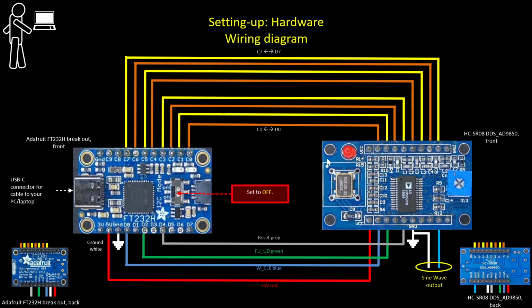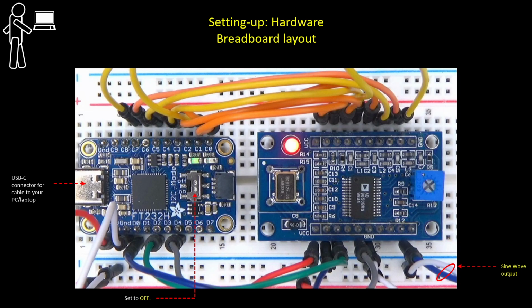This is the wiring setup that we need to join the two boards. I've tried to lay it out here pretty much as it is on the breadboard, and just for reference, I've given you the view of the back of the board so you can see the pins. That the VCC, it looks like it's here, but from the front it's there. Ground I mark in white for the simple reason I'd like to do it in black, but black on black won't show up.